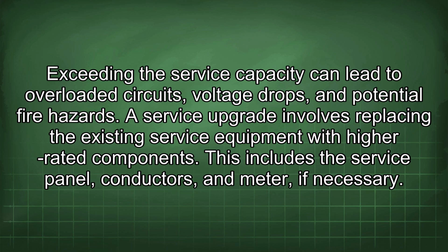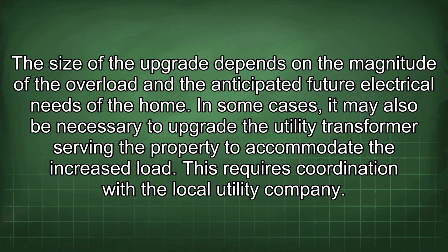A service upgrade involves replacing the existing service equipment with higher rated components. This includes the service panel, conductors, and meter if necessary. The size of the upgrade depends on the magnitude of the overload and the anticipated future electrical needs of the home. In some cases, it may also be necessary to upgrade the utility transformer serving the property to accommodate the increased load. This requires coordination with the local utility company.